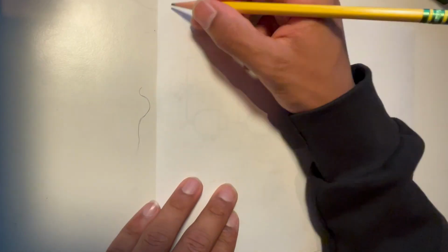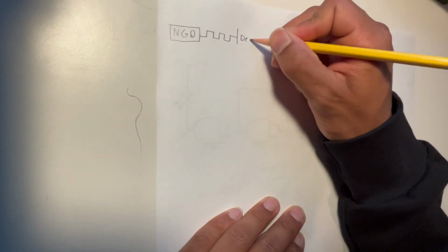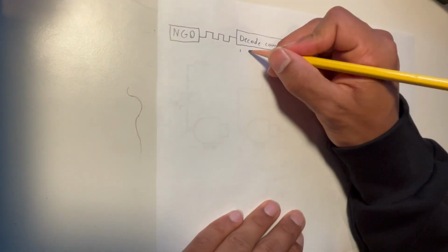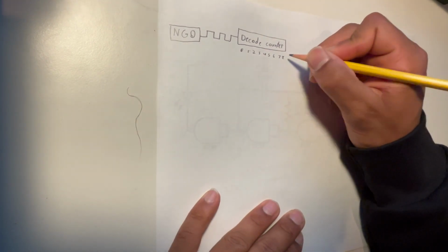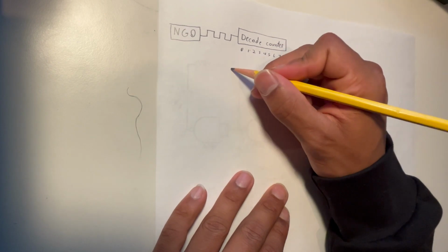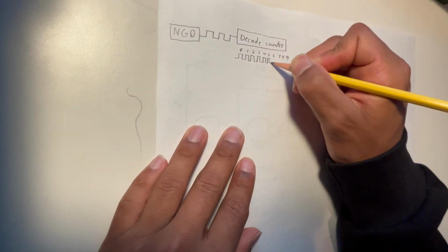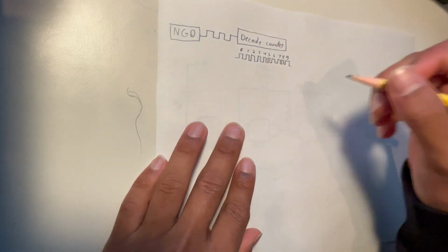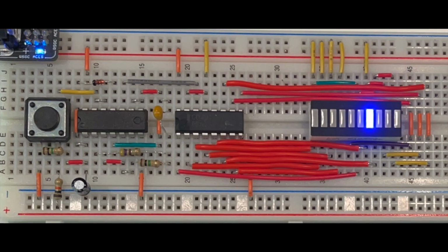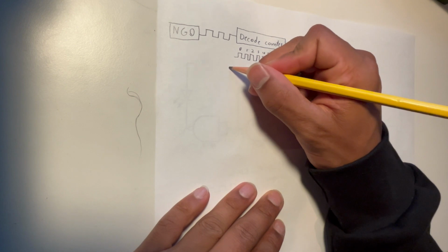The clock signal output of the NAND gate oscillator is fed into the decade counter IC. When the pins are properly conditioned, reset and enable both on low, the decade counter repeatedly counts from 0 to 9 on the rising edge of the clock pulse, as long as the NAND gate oscillator provides the clock signal. The result, when connected to an LED bar, is shown.